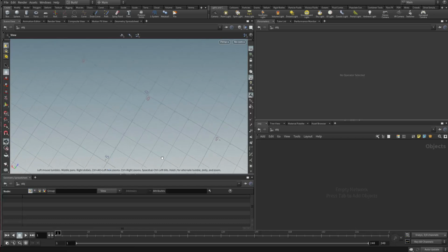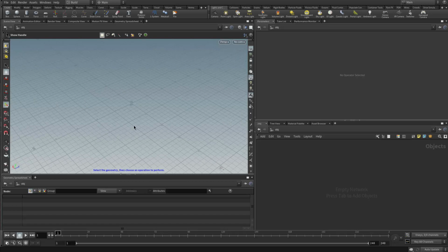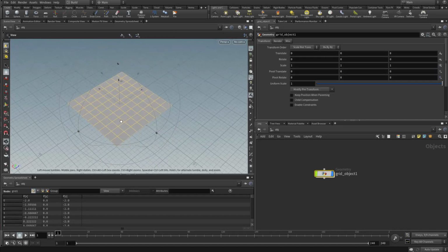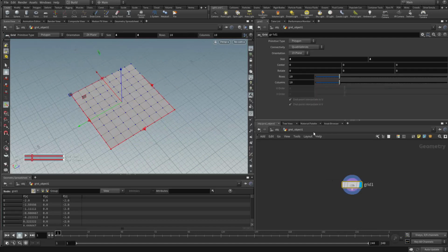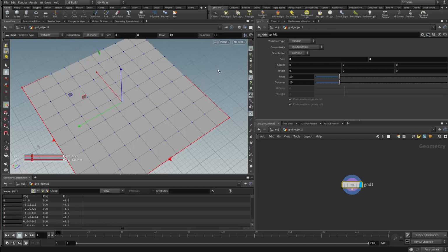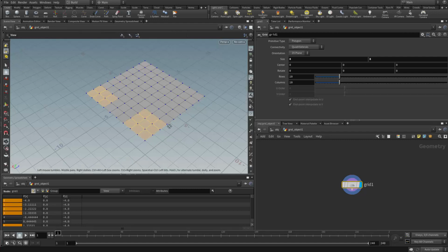In this one, we're gonna create a Houdini asset that populates any wooden kind of floor plan into a wooden floor. Okay, so something like this. If we have a grid that is basically flat on the ground and having all its lines straight, let me make it 8 times for the size, and then we can select some of the faces and then delete. This is just for testing, right?